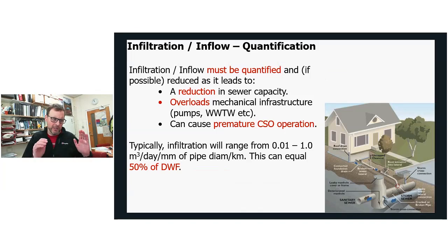So what it's saying is your infiltration is related to the time, so that's with the day. Millimetre pipe diameter, why that's important is because obviously a big pipe diameter has more space for cracks, etc. to appear, and also length, because the cracks appear over that length as well, so it can be quite substantial.